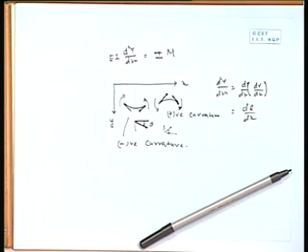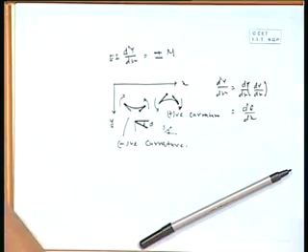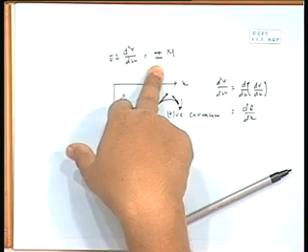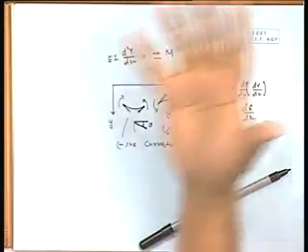Because if it is a sagging one, in terms of the xy system, your curvature is becoming negative, d2y dx square is becoming negative, because the slope we have defined is plus and minus, and the rate of change of slope, that is basically d2y by dx square, is becoming negative here and positive for the case of hogging. Now, it is a matter of sign convention. If we take sagging moment as positive, then on this side the sign will be minus. If we take hogging as positive, the sign of m will be plus. So, it is again a sign convention.